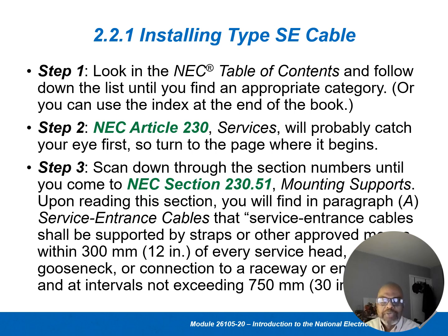In other words, you're going to put a clamp about 12 inches from the top where power is coming in. And it says the gooseneck or connection raceway, and then the intervals not to exceed 30 inches or 750 millimeters.